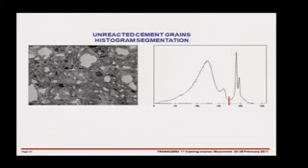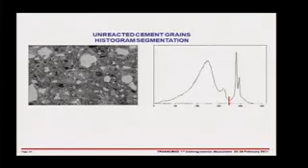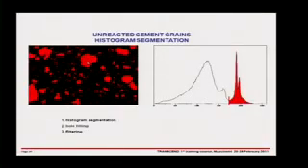So for the anhydrous cement, it's really quite simple. We just make a threshold at this point here. We segment the image. We can do a little bit of cleaning up. So, for example, when we segment here, we may decide to fill in the holes, etc. And then we can measure the amount of unreacted cement in this image. And when we measure the unreacted cement in that image, we see in this image it's 16.15%.